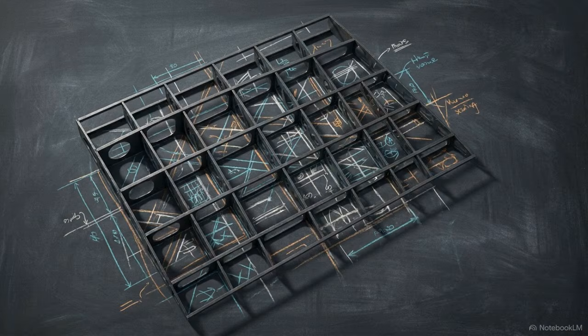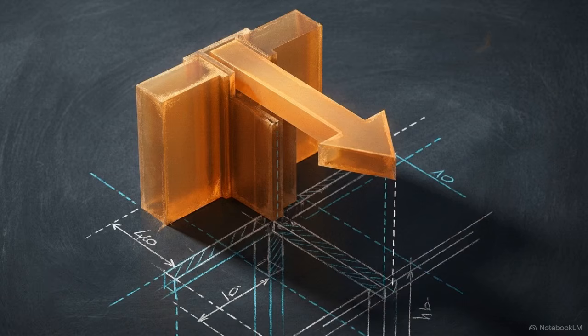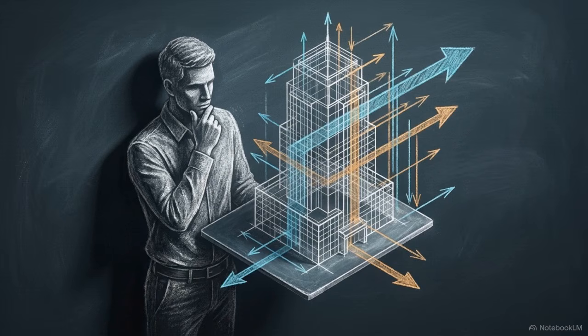In full spatial non-parallel systems, force vectors move across all three dimensions simultaneously. Finding the 3D magnitude requires a single equation, the square root of the sum of the squared x, y, and z components. The final direction of the resultant in space is determined by those resulting x, y, z coordinates. Spatial force systems do not require new laws of physics. They are mastered through the rigorous application of three-dimensional orthogonal decomposition.